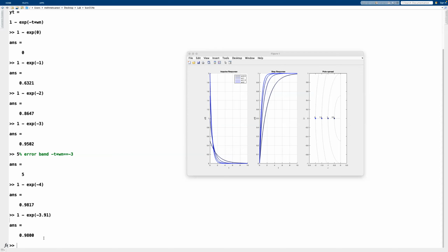Now, rise time, peak time, and stuff like that for a first order system are related with the same relation as the settling time is, because you can use the exponential term here and analyze how much time it takes to rise from 10% to 90%, or sometimes the definition changes from 0 to 100%. Then you can use that for rise time. Giving a peak time here doesn't make that much sense because the peak value is going to be the steady state value. So that's also another interesting topic.